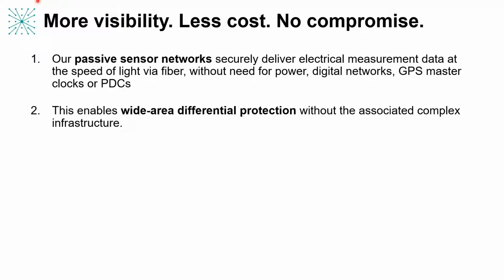And once you have this high quality synchronous data available at a central location, this allows you to operate robust differential protection schemes over a wide area without the complex infrastructure that's normally associated with such a scheme.